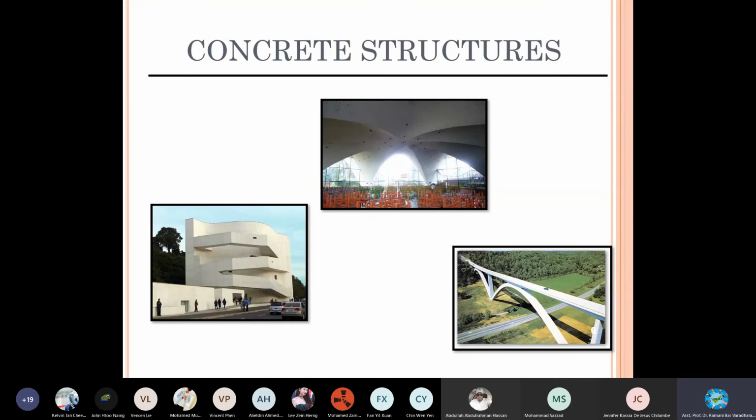I think that makes the difference in the color of the plastering. The reason here is iron content will be more. If it is reddish type, iron content will be more. And it is susceptible to temperature, susceptible to decoloration. Decoloration is very fast. You need plastering quite often, proper white color finishing often, to hide this fading of the color. Maintenance will be more with these types of materials. This is my understanding. If you have any other answers, you can bring them to me next class.